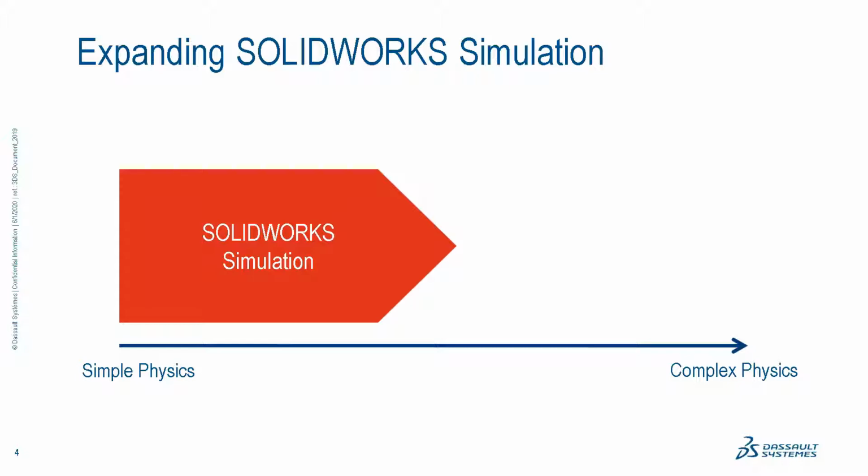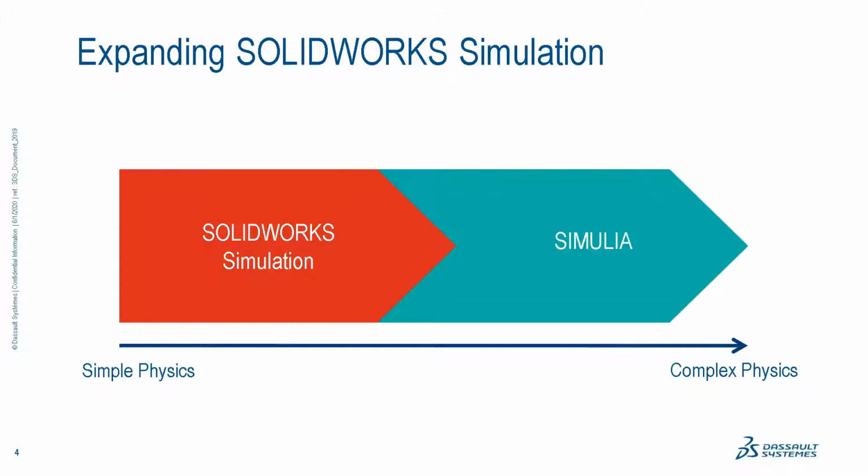And if we're being honest, there are just some situations where the desktop SolidWorks Simulation Premium offer hits its limits. The alternative to that, at least in the Dassault family, is the Simulia offering. If we just focus on finite element analysis, really Abaqus, there's nothing in that space that Abaqus can't do. It's an extremely powerful tool. It's got really advanced material models. The solver itself is written to take advantage of multiple cores, so it can be really fast.